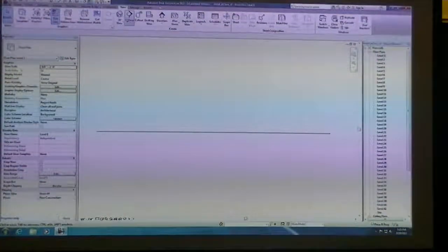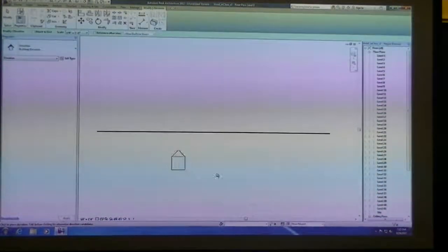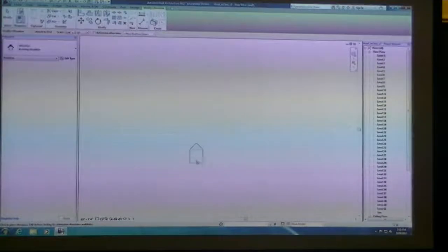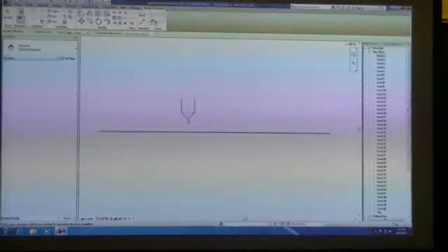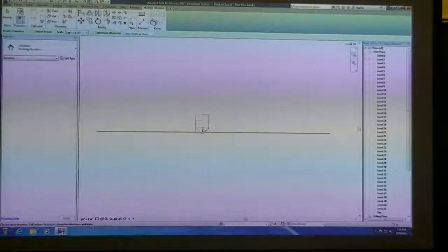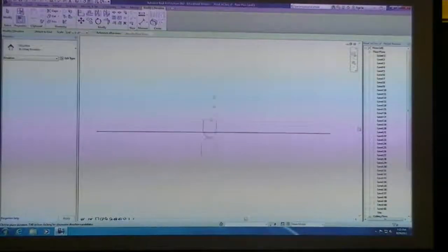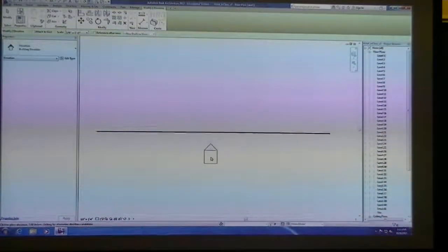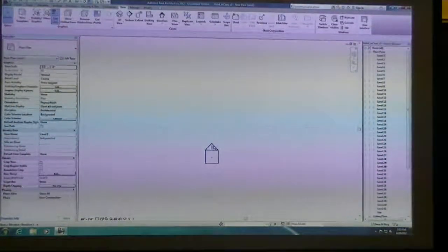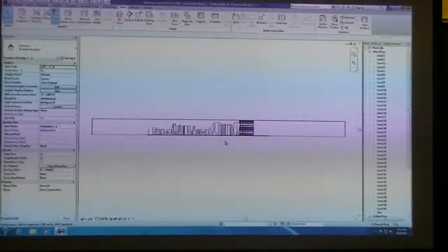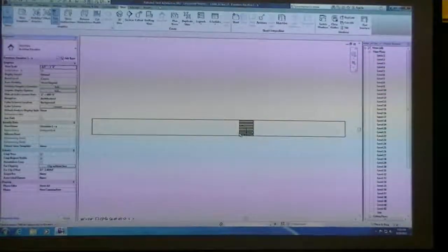We can click on View and then Elevation, and when you start to hover over the screen and you get close to your wall, you'll see that your elevation view arrow starts to point directly towards whatever you're trying to take an elevation of. I'll just click on it, and then you can double click on the arrow, and we're going to have to hide this site.